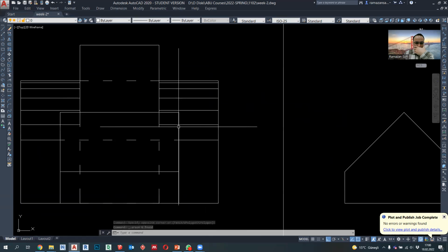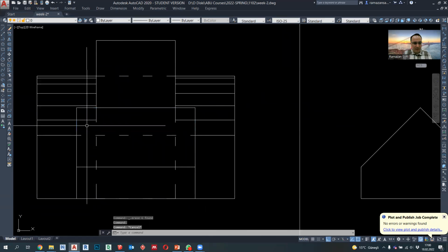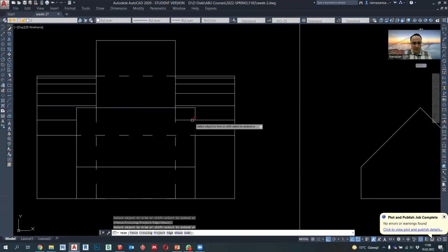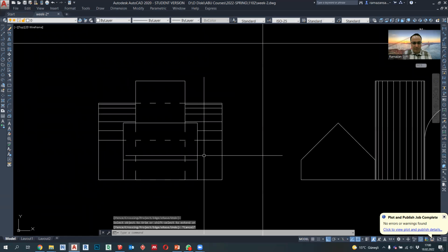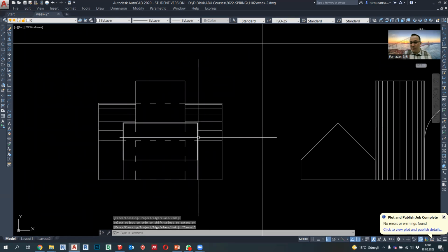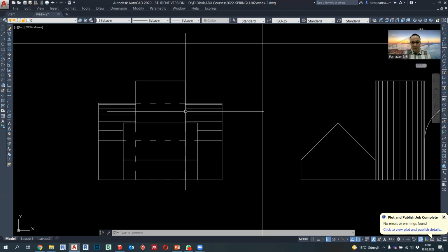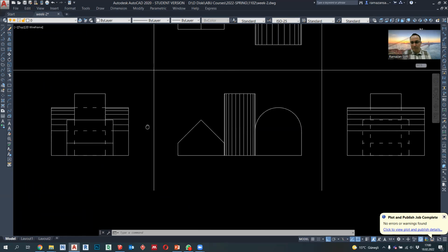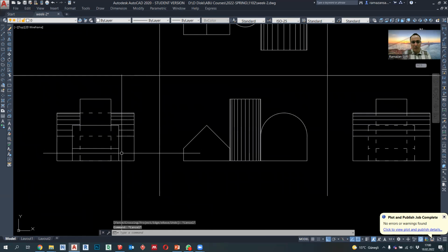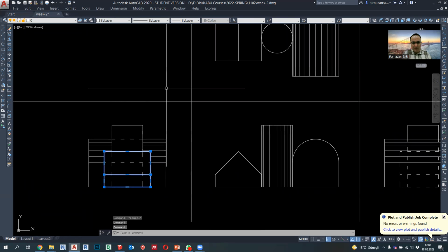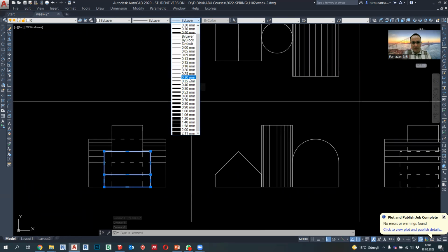Let's make settings here. You see, this object at background, so we must delete this line also. Only present the edges. These are the surface hatching, so you shouldn't extend as dash line here. Okay, pay attention. Now, the objects which are close to us will be thick line.